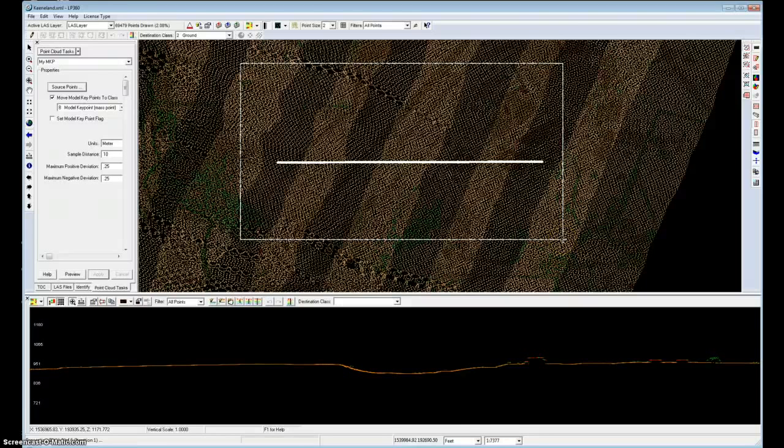And you'll notice the processing information that we have in the lower left panel of our key, processing block 1 of 6, running iterations, and so forth. So this will take a little bit to process as we calculate what points are really needed to give us a good surface model with respect to the ground. So again, in the curved areas we'll need quite a bit, and in the flat areas we'll have a low point density, and we'll see that occur in just a moment.